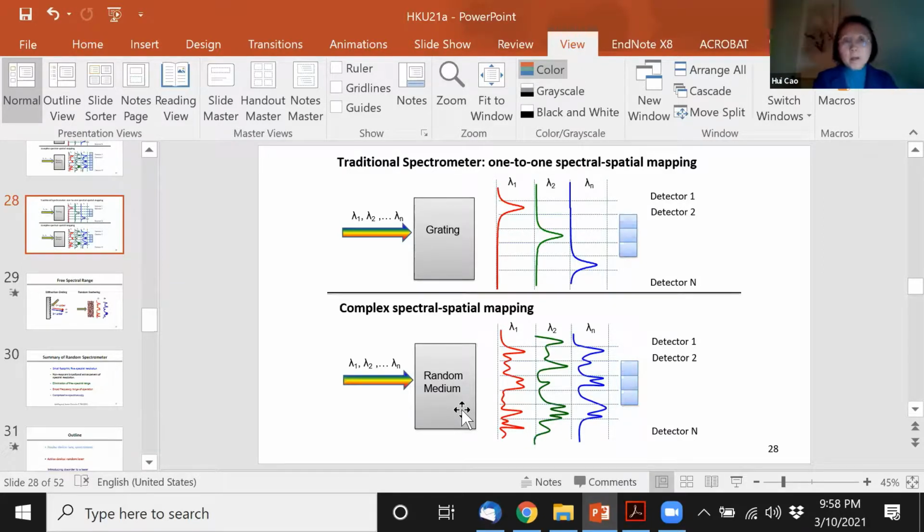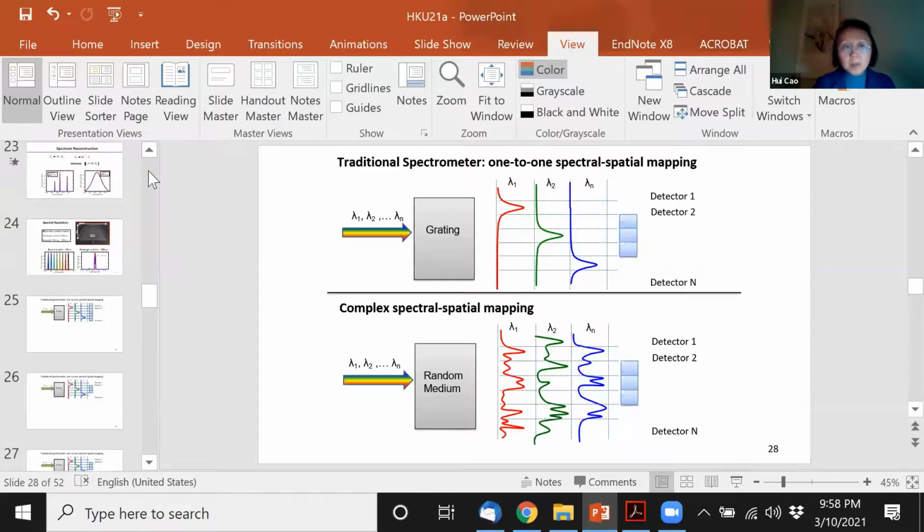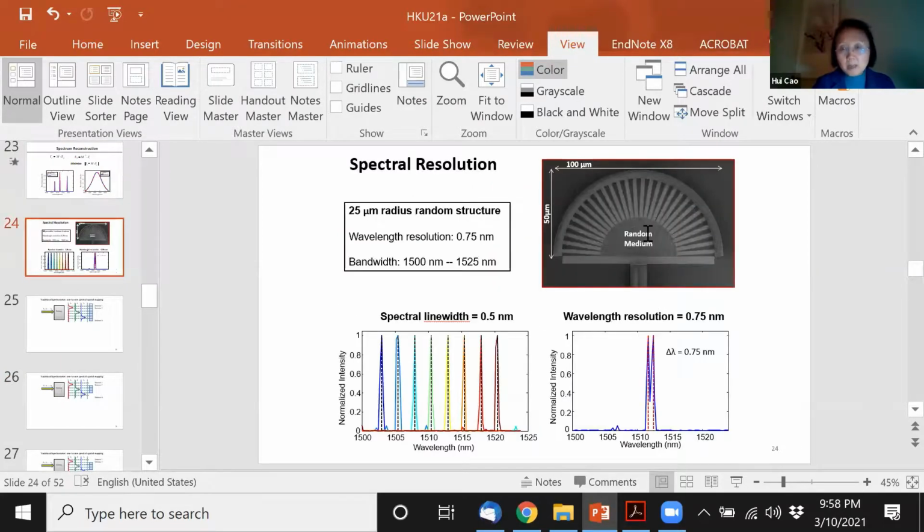Yeah, right. For a spectrometer, that's why we try to make it on chip. Because if you make it on chip, your scatterers and everything are on chip. That's much more robust, right? The only thing that can change is temperature. But for those chips, you have this kind of packaging which you can get from SOAR lab. They can keep the temperature to 0.01 degree, so you can stabilize the temperature. If you fix all the scatterers, at the end of the day what matters is only the temperature drift. Or you can calibrate your device for different temperatures. You can store everything in the computer, then use a different lookup table for the temperature at which the system is operating. Right. Okay. Thank you.